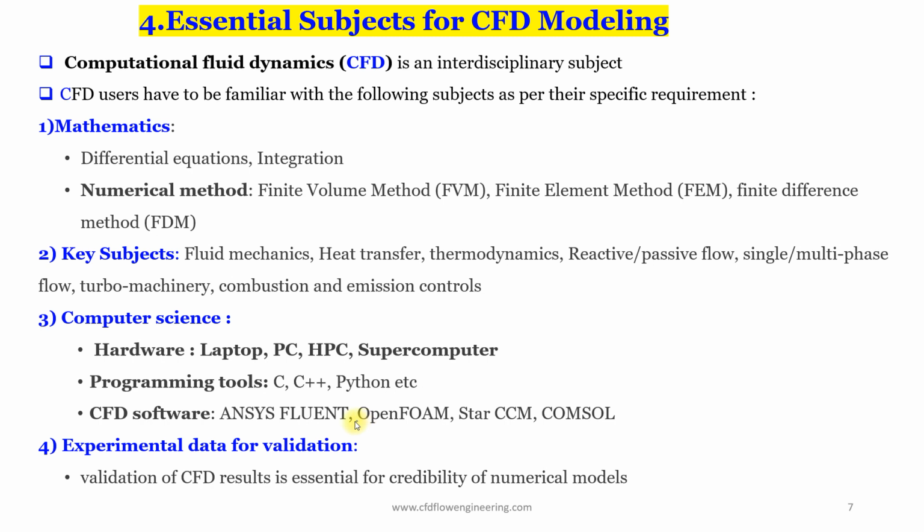The next, experimental data for validation. CFD results should be validated to build confidence. Otherwise, it gives colorful results which may be beyond reality. And to check it, experience matters a lot. Practical data may help to guide CFD.